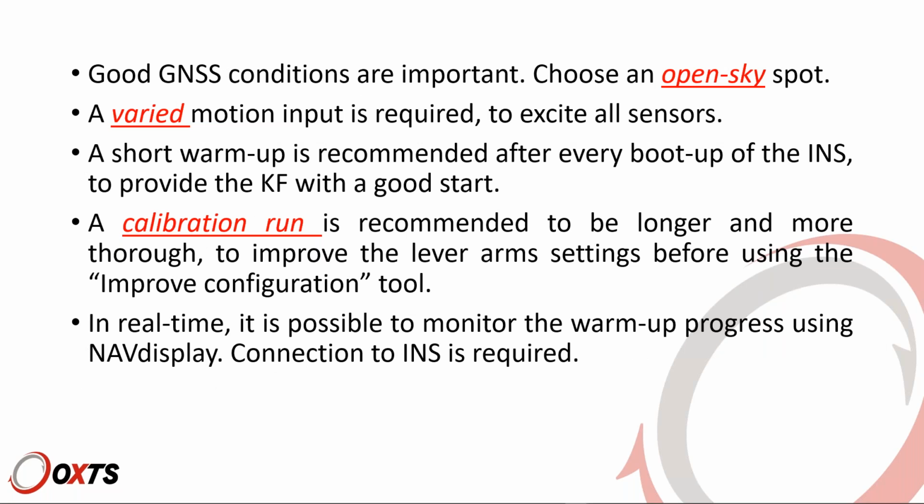Optimized configuration means the one that you get through the calibration run. So the one that you use to optimize your config starting from a loose configuration. During the warm-up, you need to have good GNSS, so an open sky spot, and have a varied motion to excite all sensors. So if you are starting from an optimized config, a short warm-up, 2 minutes, is enough.